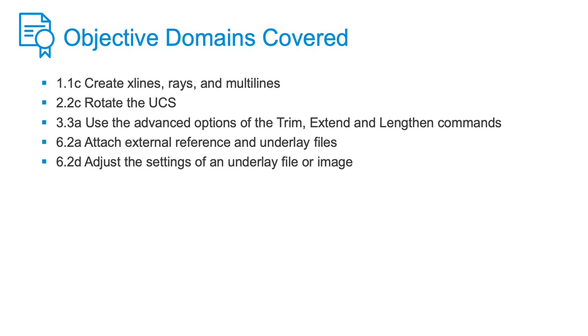In this video, we reviewed some techniques to use when creating and modifying multilines. I used an attached image as an underlay to help me place my MLines. I adjusted the image's appearance using the fade control on the ribbon. I created a couple of multiline styles using different colors and line types. I used the Extend tool and the ML Edit command to modify my multilines. I also used Properties to modify the line type scale used by the multilines.